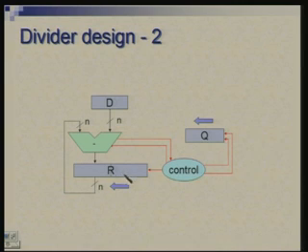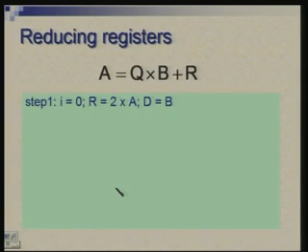We have R shifting to the left, okay, and as the positions get vacated here, we can keep on stuffing the bits of q. So, we do not need to keep a separate register for q, and can utilize the part of R towards the right hand, which is getting vacated, to accumulate the bits of q. So, that is a very straightforward change, and we have omitted register q here.